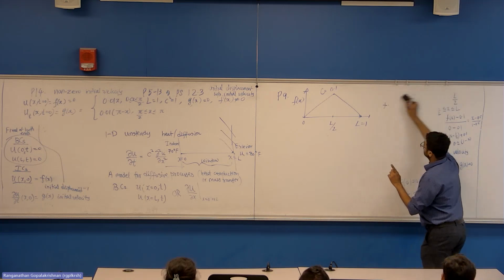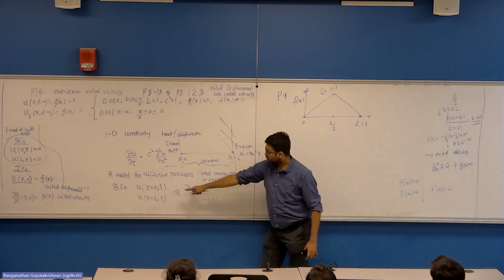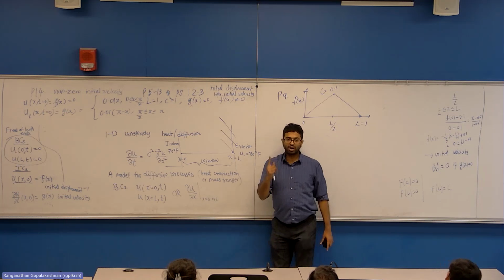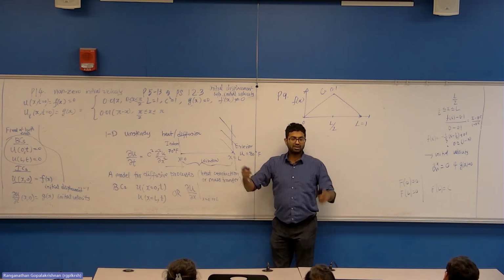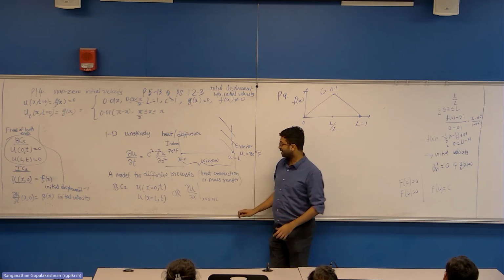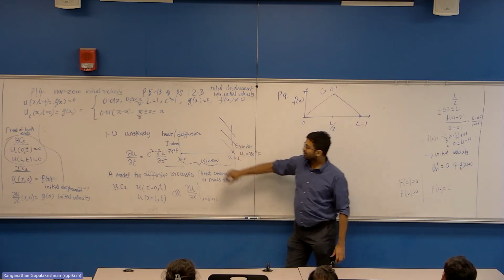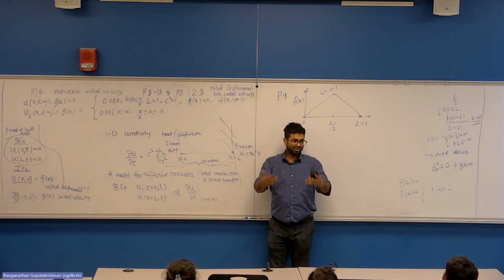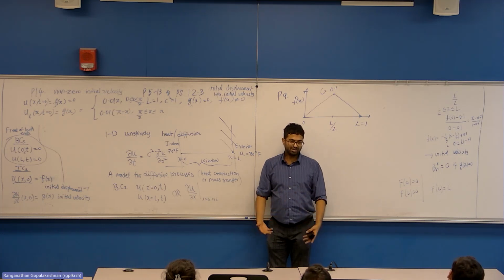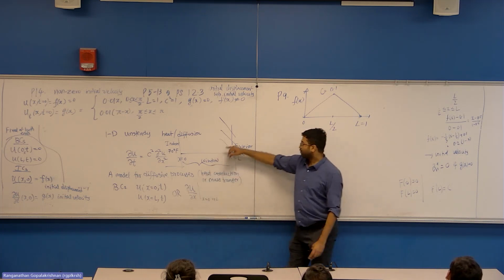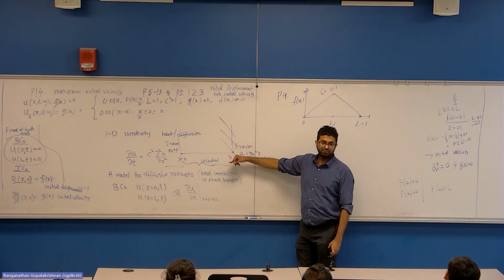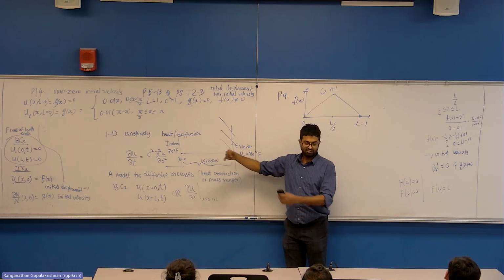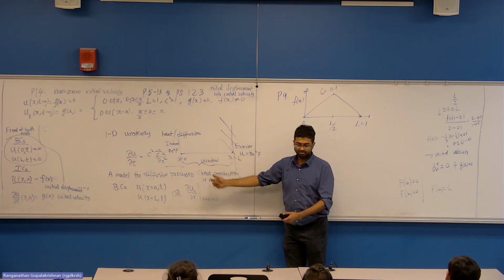Oh, wait, sorry. So I talked about boundary conditions, which could be Dirichlet or Neumann. Usually there has to be at least one Dirichlet boundary condition. You can't constrain both the ends with only heat flux. It's like saying, I'll put a heater here, I'll put a heater here and supply heat into the material from both sides, that's untenable. At some point, the material is going to fail. Right? So one of them has to be a temperature boundary condition if you were to get a finite valued solution that is mathematically making sense.